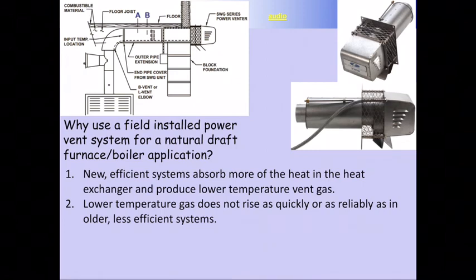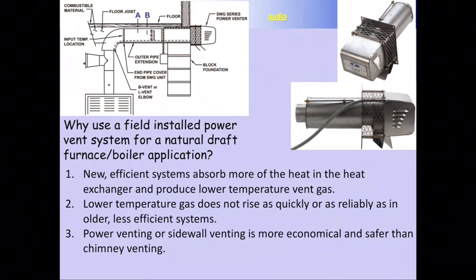I could have a problem where I just can't consistently get the appliance to draft correctly, and I'm constantly running into problems where I may be having limits and safeties that are causing failures. You could even see it where the customer might say we keep having problems where my carbon monoxide detector is giving us issues. And again, those are all serious issues you have to address and try to deal with, but it is something that you can look at.